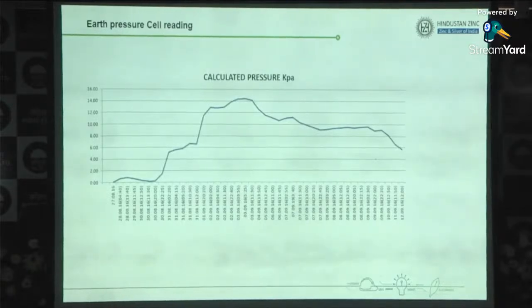Piezometer we are installing, like I told, sir, in the paste fill we do not have. We had a hydrofill plant, but it has been dismantled two years ago. So we have completely shifted to paste fill, and in the paste fill we do not have an issue of water, so we are not installing the piezometer. But we have one huge capacity tailing dam, and there we are installing this piezometer. But this EPC, we are installing on the barricades.